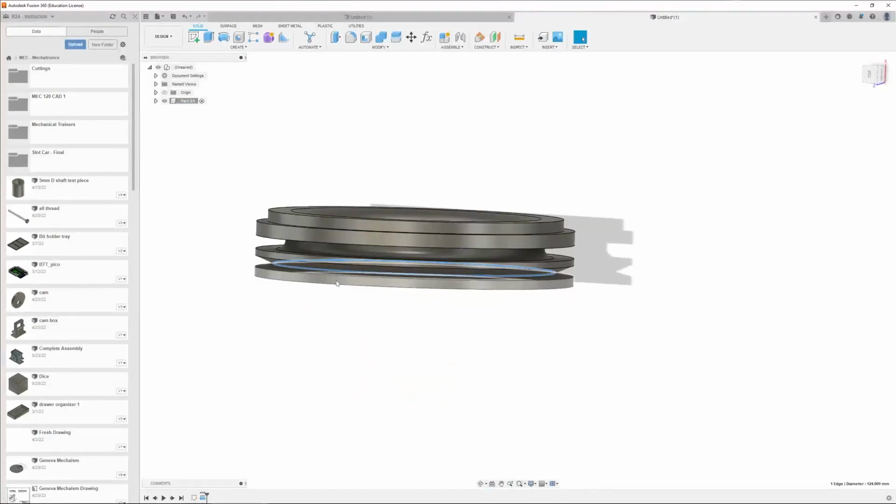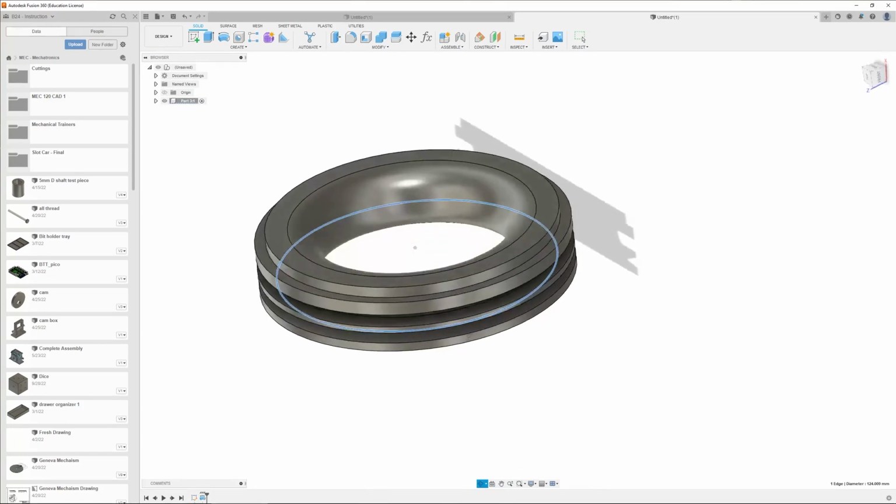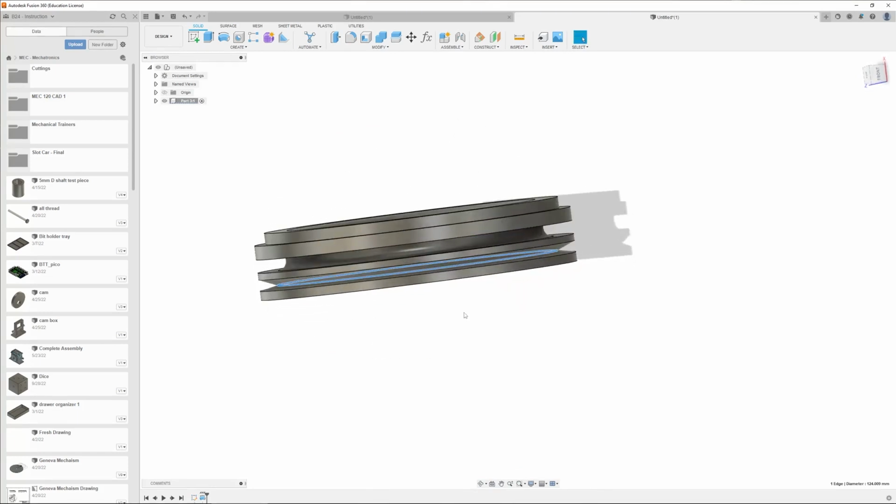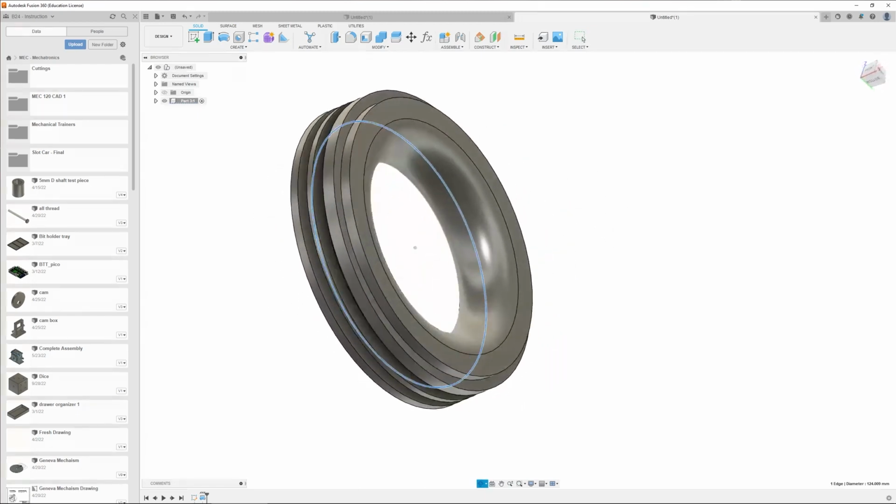And so if you're in a situation where you need to make grooves in circular parts that have lots of O-ring or gasket seals, snap rings, etc., the Revolve tool can greatly simplify and increase the speed of your modeling by using the ability of the Revolve tool to create a profile and then create circular geometry with that profile. So something to keep in mind.